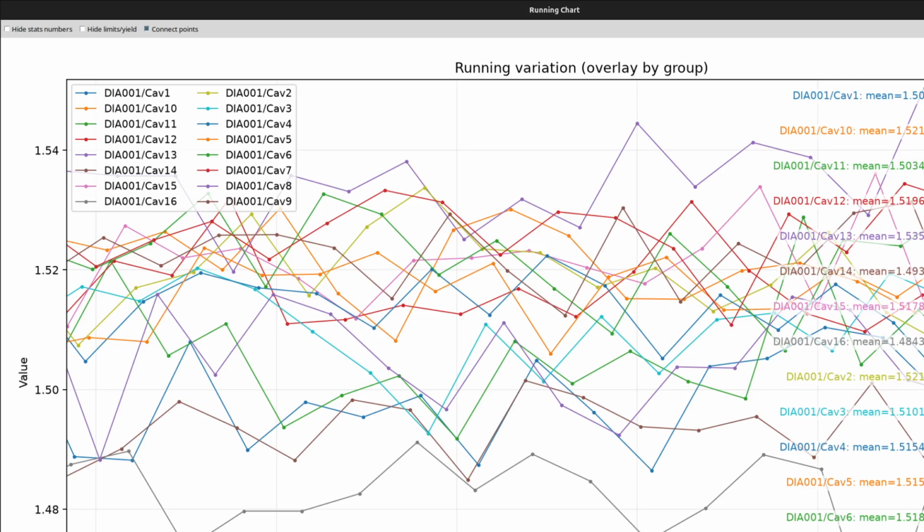I don't know what the actual cavity is here, but this process of setting this up where it does the fast Fourier transform tells you the number of cavities, and that lets you line it up so that you're seeing the variance of just the cavity, what the process capability is of a single cavity in here.